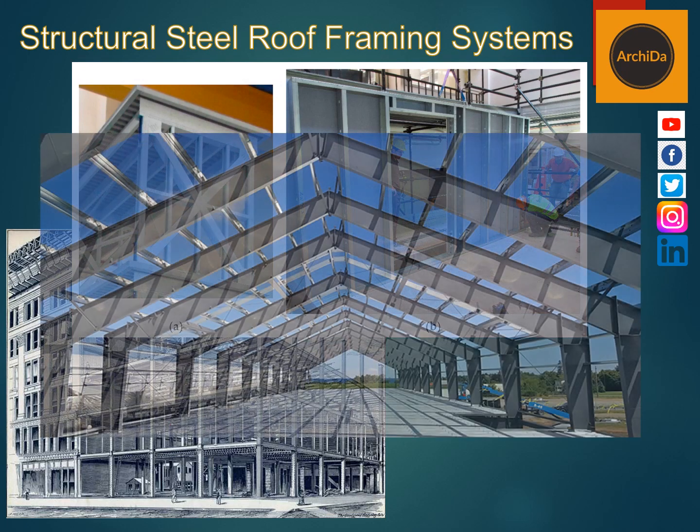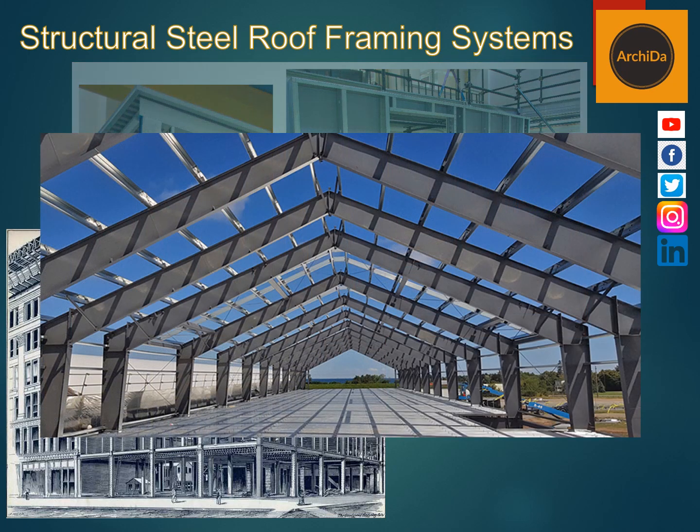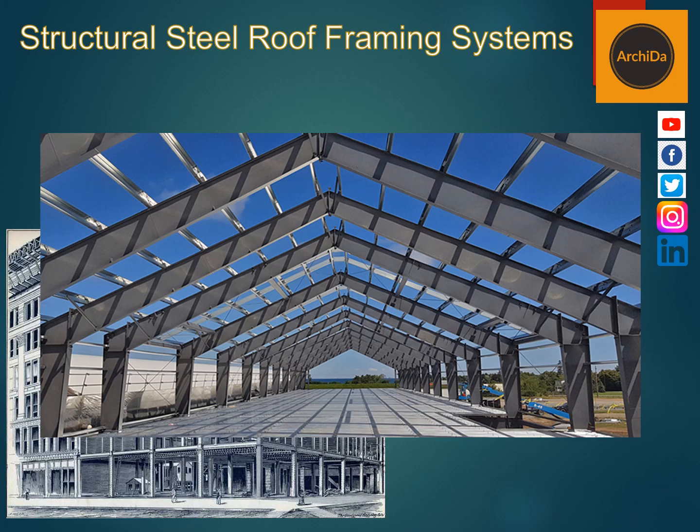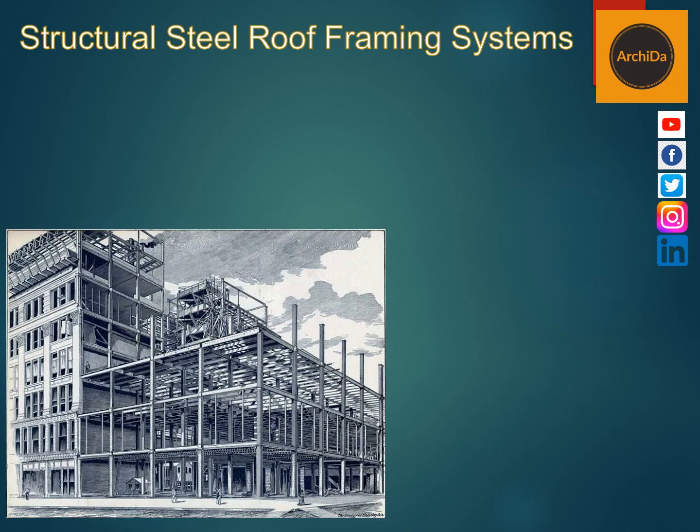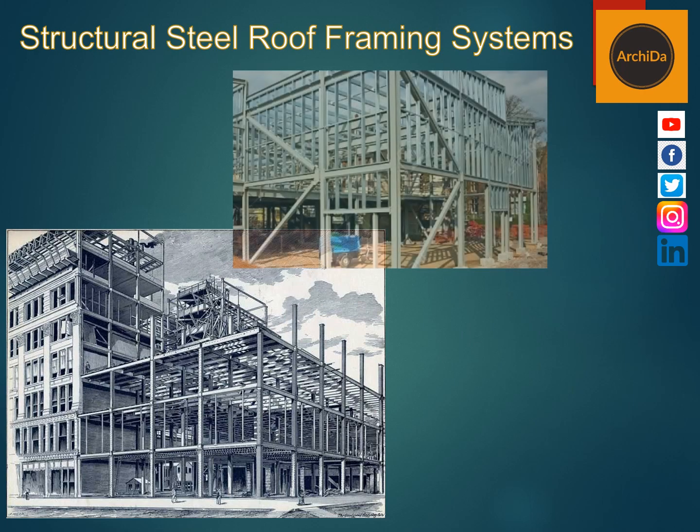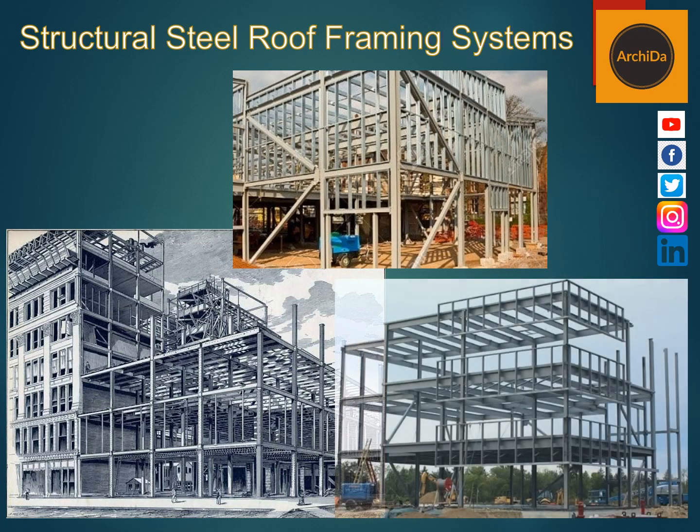Now for the skeleton steel framing system, the skeleton steel frame is composed of steel beams and columns which are connected using the proper connections. Steel beams around the perimeter of the structure are termed spandrel beams, on which masonry walls are placed. It should be known that all gravity loads in skeleton frame structures are supported by beams and columns. The distance between columns can be established according to the functions and requirements of the structure.